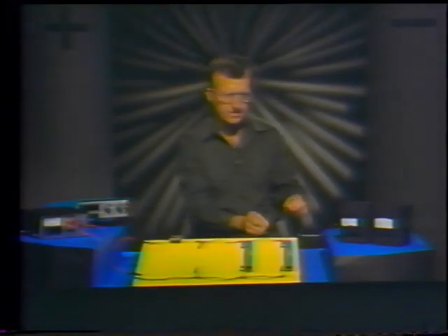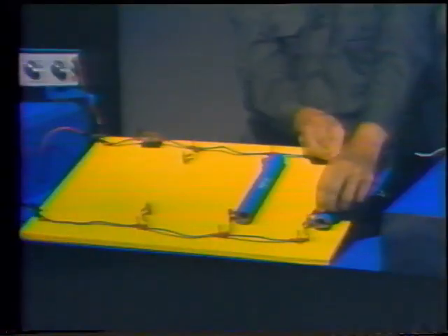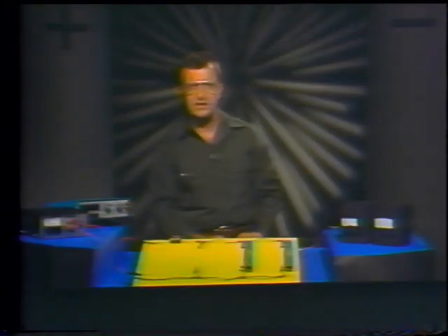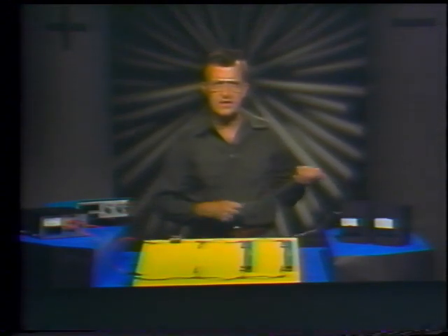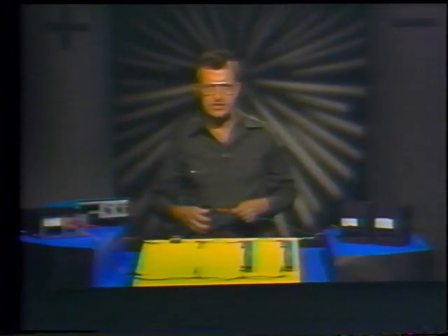How about the resistor on the other branch? Okay, the meter reads 5 volts here too. Okay, that proves our first fact. The voltage across each branch of a parallel circuit does equal the source voltage. Let's move on to the second fact. The total current in a parallel circuit is equal to the sum of the currents in each branch.